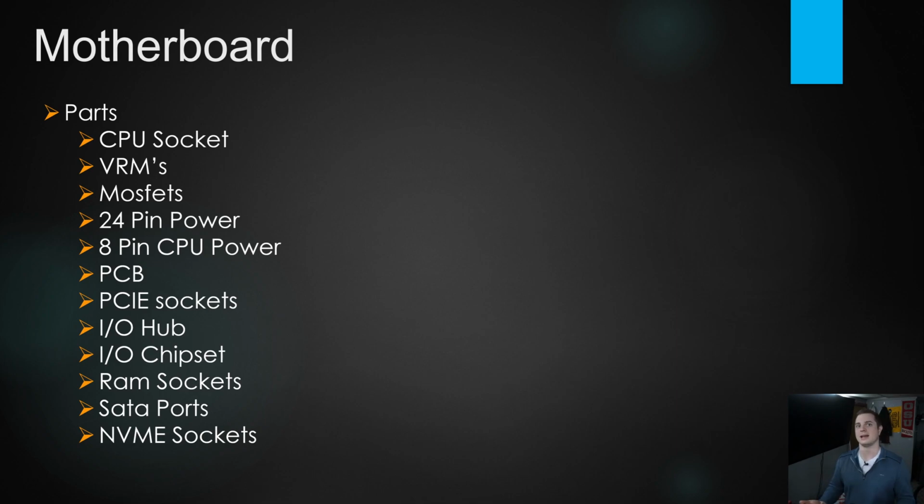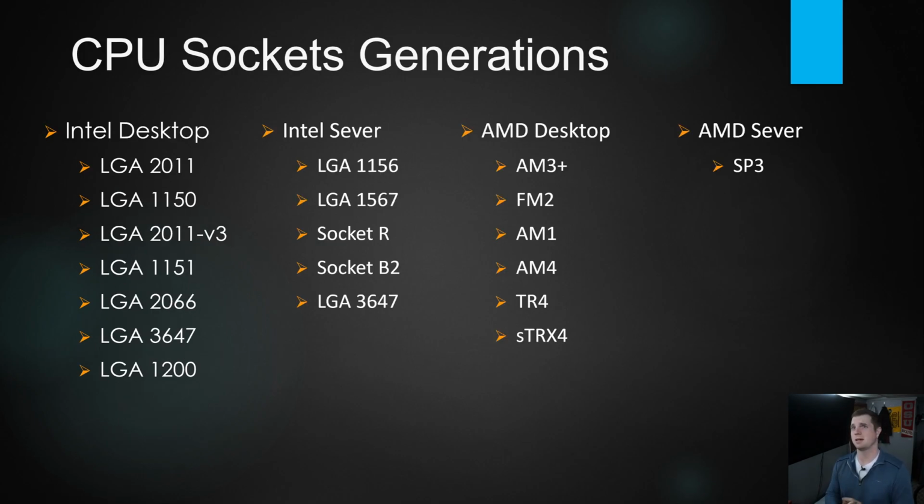So your high-end $1,000 consumer motherboards are going to have a very different VRM and MOSFET setup compared to your budget tier, and that is because they're trying to account for overclocking ability. Consumer motherboards at the high end, at least, are bought by enthusiasts that want higher performance, even if it doesn't matter. It's there because it makes us feel better about the components themselves, regardless of whether we actually need it or not.